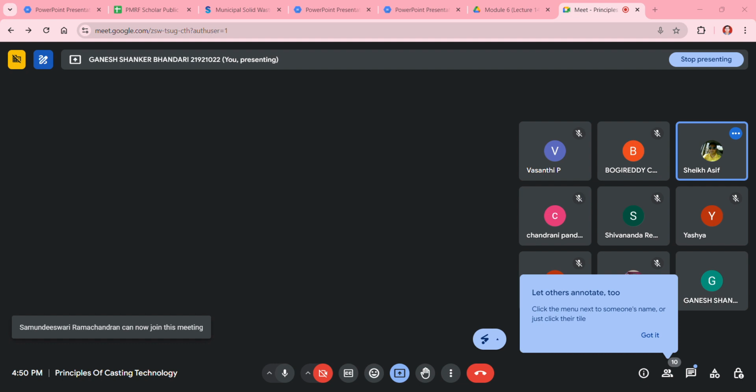It is time required per week, as a function of the round trip haul distance for hauled container system. So the formula you are going to use is this: time per trip, then multiply by 7.